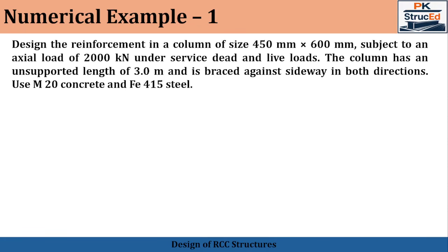So with this background, let us consider numerical example 1. Here, we are required to design a rectangular RCC column of size 450 mm by 600 mm, which is subjected to an axial load of 2000 kilonewton under service dead and live loads. The additional data provided are: the unsupported length is 3 meter, the column is braced against side sway, the grade of concrete is M20 and that of steel is Fe415. So this is a typical interior column in a multi-story building.